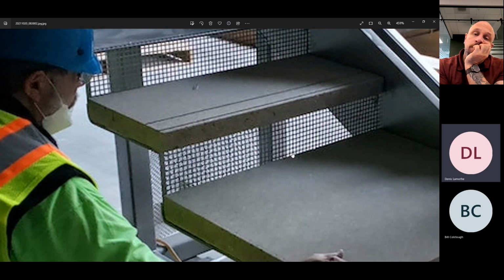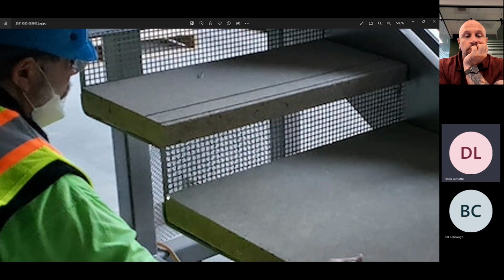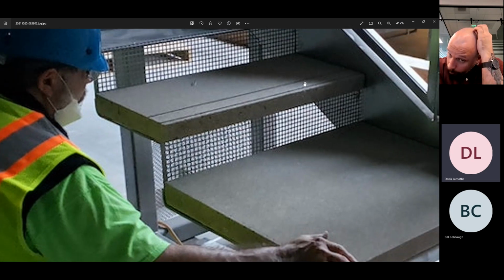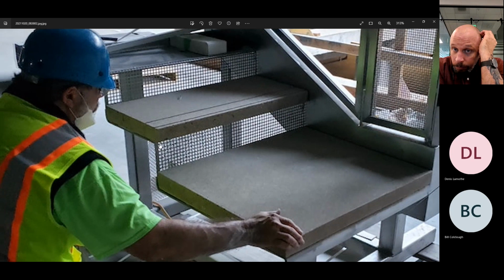The riser that you're seeing here is a perforated panel stainless steel that was welded separately from the tread. So this panel would be bent with a slight overlap on top of the tread, and then just kind of stitch welded to hold it in place. So the main structural component here was, I believe, probably around 3/8 thick plate. It was just bent, and that's what allowed us to apply this precast terrazzo on top.